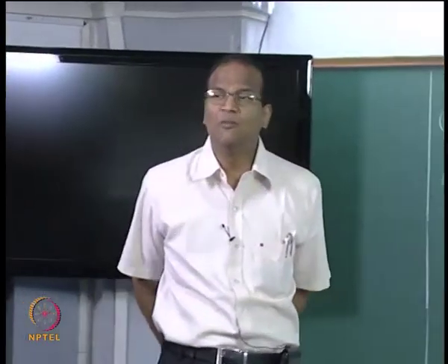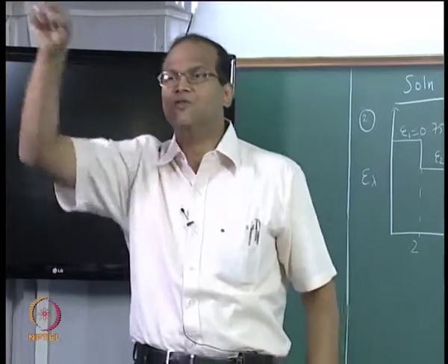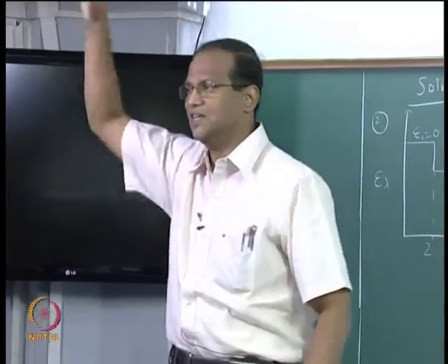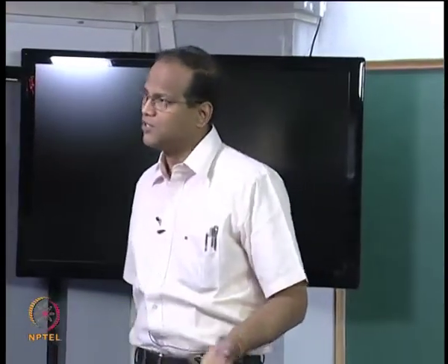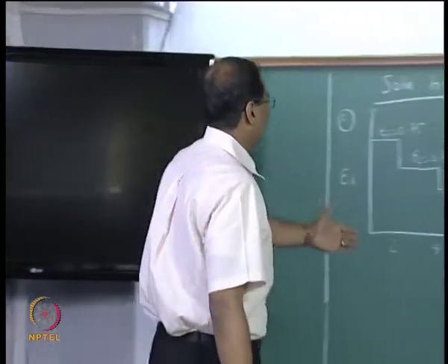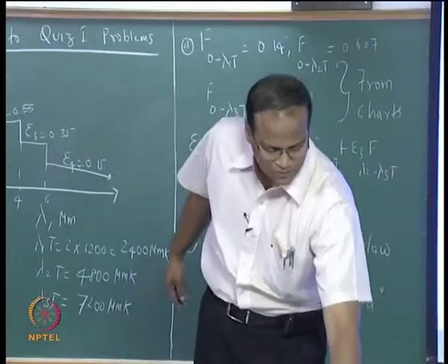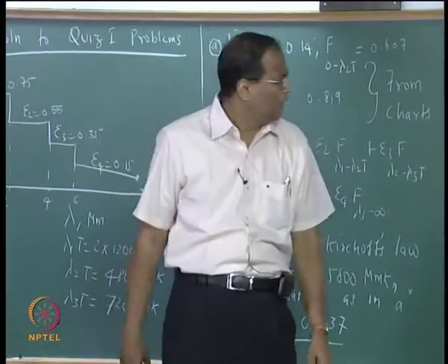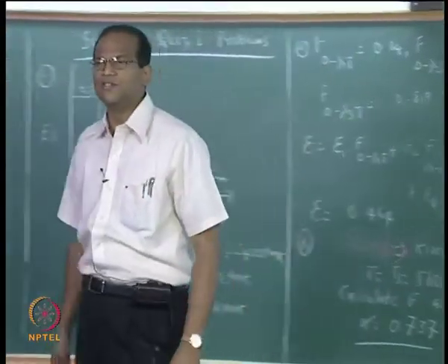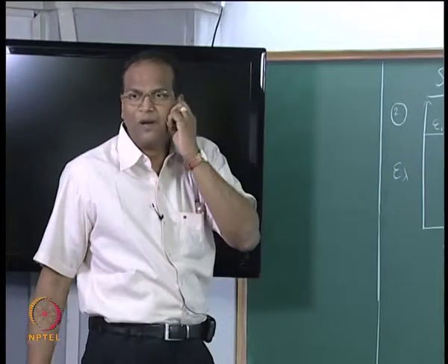Otherwise I should give you information on I lambda. I would say it increases from 0 to 4000 watts per meter square, decreases, increases. Since I have not given the distribution, you have to use the black body function and repeat the same procedure, except that you will use 5800 Kelvin. Now we got the alpha. So 6 marks plus 6 marks, 12 marks.